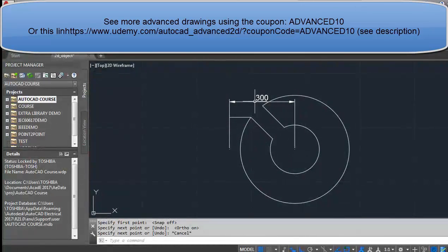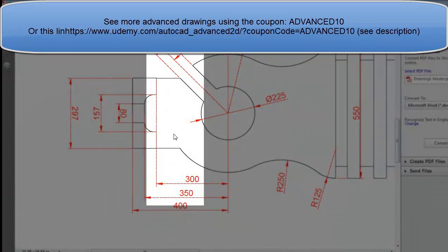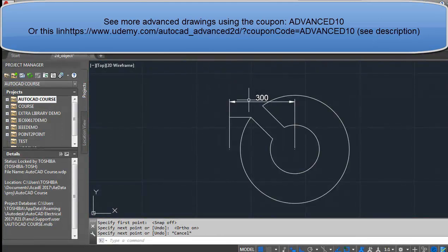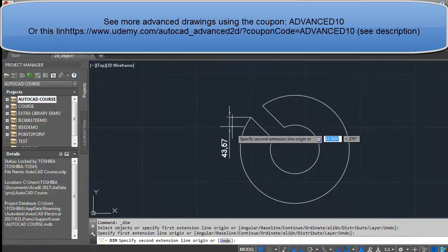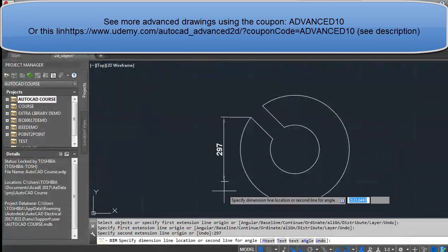this dimension, we will see that we trimmed a part of the circle again from this point to this point, and we have a dimension as 297 from those two lines here and here. So let's go 297 from this point. Let me remove this now, and again from this point vertically 297, and here it is.